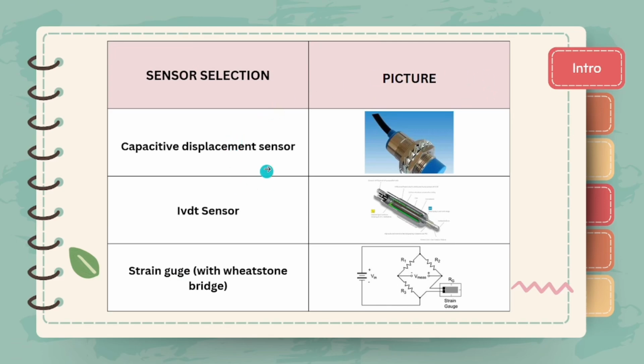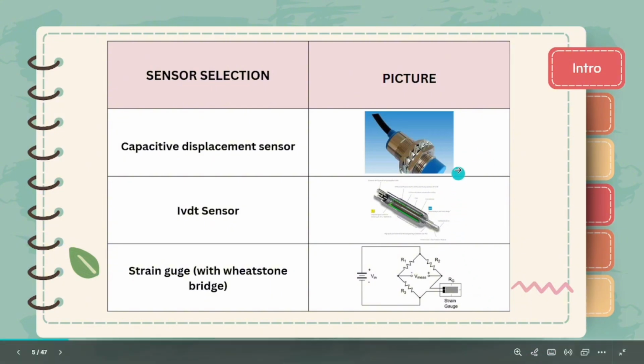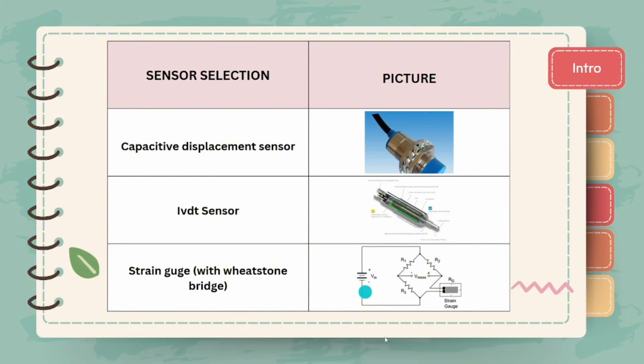As we know, capacitive displacement sensor is used to measure distance and also displacement. This shows how fast something can move. This capacitive displacement sensor actually works like a capacitor. It's best for very small movement and high precision. As for the pros and cons, the pros are that it is very sensitive and accurate, and the cons are that it can be affected by humidity and temperature.